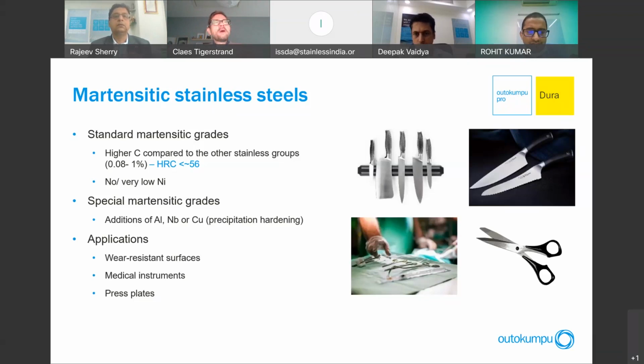So for high pH and alkaline environments, and hot nitric acid, you should select a grade with a low molybdenum content or without molybdenum. Then it's better to go for a lean duplex grade, for instance, or standard 304 in some cases.